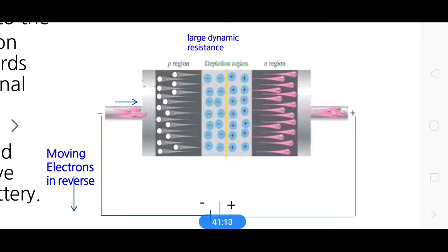If any charge carrier is moving towards the junction only, there is a chance for the current flow in the reverse bias. So you can see the clear picture. The holes and electrons are moving away from the junction, and the barrier potential is increased, means there is a heavy opposition for the charge carriers. Finally the resistance of the diode increases.